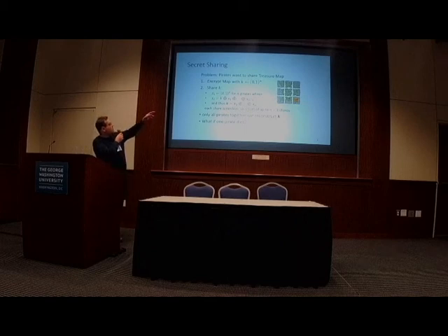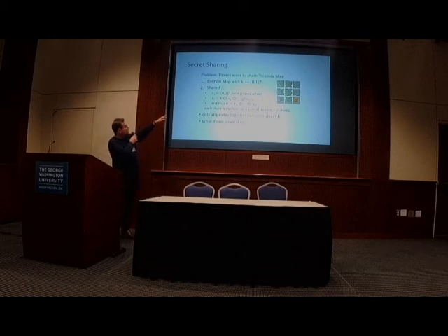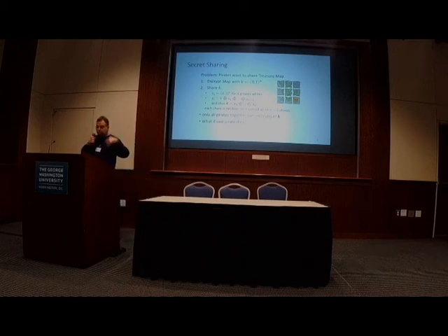Basically, you take a secret, let's say K, that you want to hide and break it into shares. You pick random masks x_i and XOR them over progressively to obtain these single shares. By doing this, you're splitting the secret K into n different computation paths, and if you can compute with them separately to mimic the original computation, then you're able to do the computation by masking.